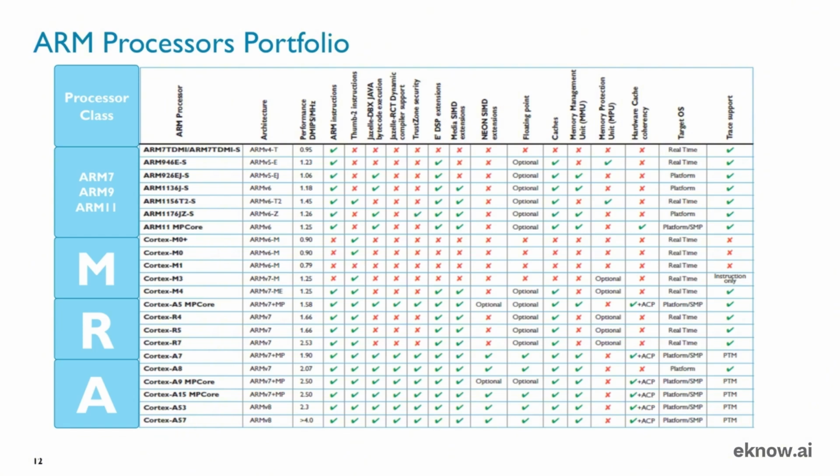As we move across, we see columns for different technologies. For example, Thumb-2 instructions. A checkmark here means the processor supports this instruction set, which is a mix of 16-bit and 32-bit instructions designed to give good performance while keeping the program code small. You'll notice the Cortex-M processors all use Thumb-2, as they often go into devices with limited memory.